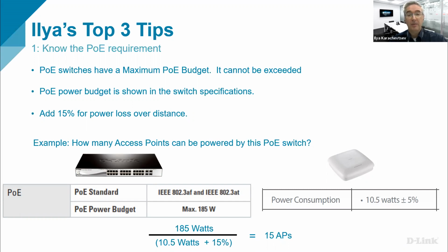So that's something which we see quite often, and whenever we work on or design a project, we always check with the customer what type of PoE devices they're connecting and how many of them, and we can look up the wattage requirements for these devices, so we can recommend the right switch for the right solution.